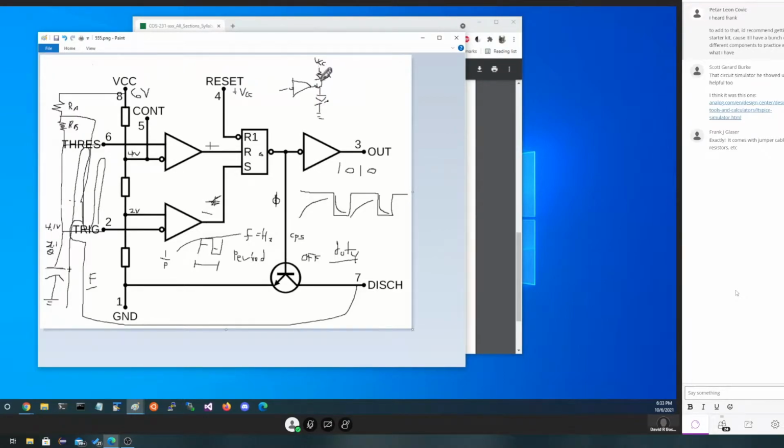So therefore, yes, this will continue to show 5 volts here, but on the other side, 5 volts across this certainly gives us enough. And as long as we have the resistor here to hold back the current, we would turn this on. So if the output of this is high, this LED is on. If the output of this is low, that LED is on. So we can choose one of two to be on based on whether this is a high or a low signal. Of course, we might just do one or the other.